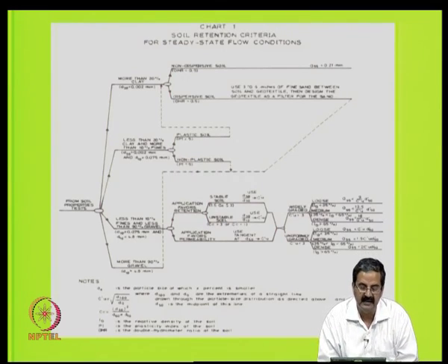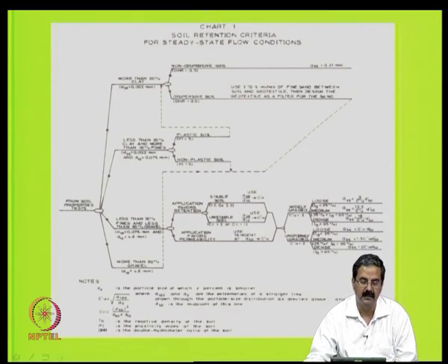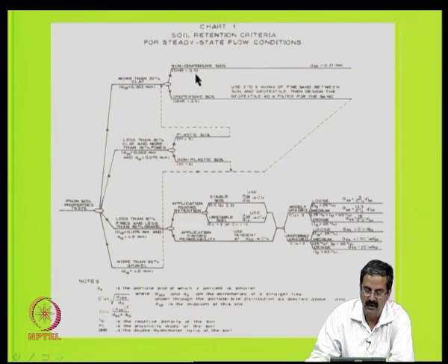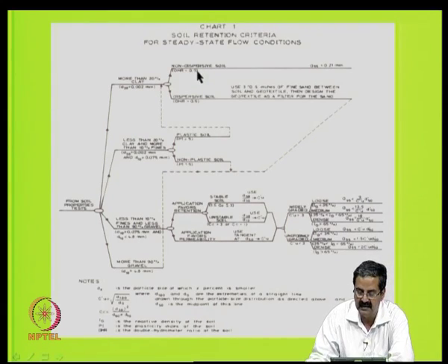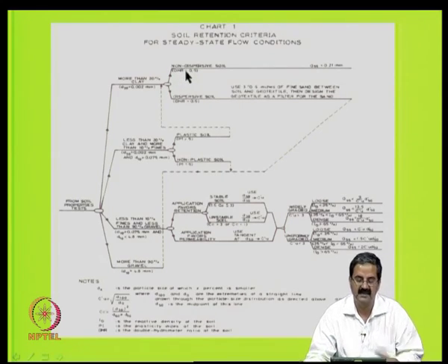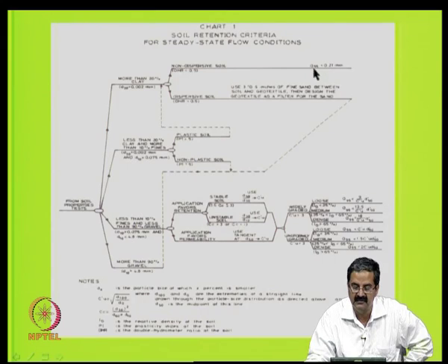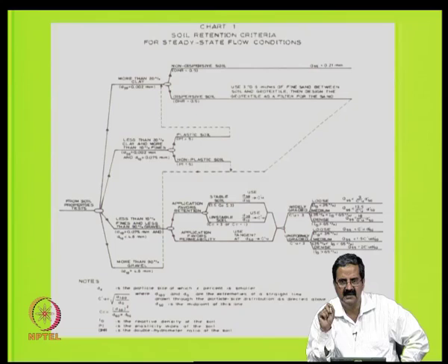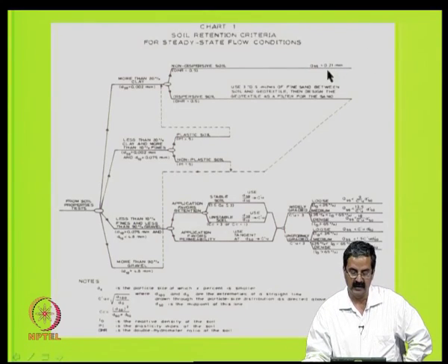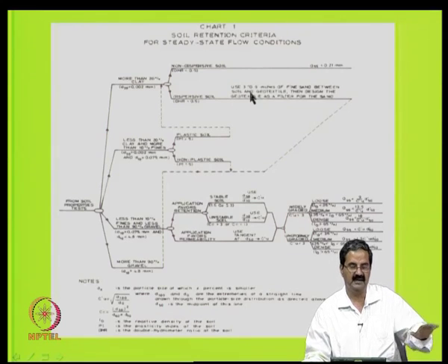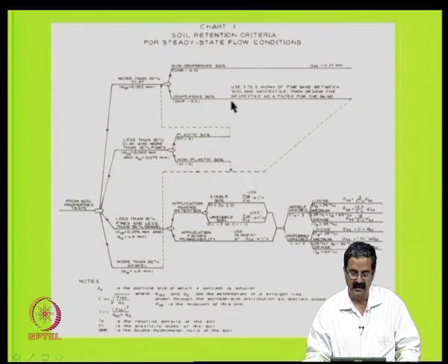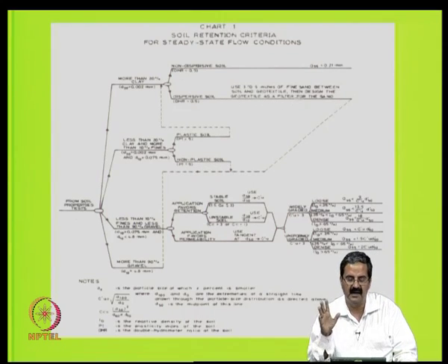So, you want to really check this clay. The moment the soil testing results show that it is more than 20% clay, you have to see whether it is dispersive soil or non-dispersive soil. There is a test for it, called the double hydrometer test, and based on the test you get some result. If it is less than or equal to 0.5, then you have to provide an apparent opening size of less than 0.21 mm. The geotextile size will be so fine that it gives a size of 0.21 here. If it is somewhat dispersive, then you have to put a cushion of 3 to 6 inches of fine sand between the soil and the geotextile. If the material is so dispersive and has a tendency, you need to put a cushion and then put a geotextile, otherwise even the geotextile may not be effective.